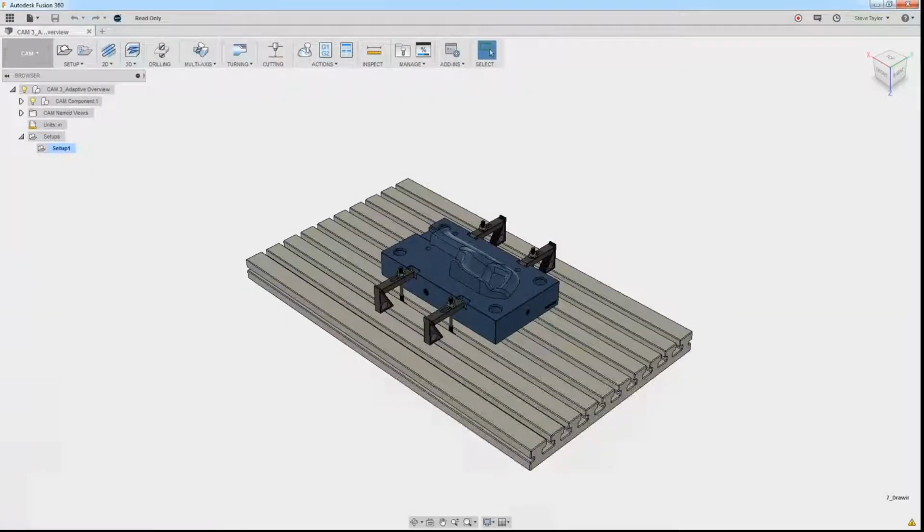We have the same setup orientation as we did before. By using this standard model, we ensure that we didn't make any mistakes that are going to carry through to this. We don't always have to start out with 2D toolpaths, but for this one, we will do an initial 2D toolpath using a 2D face.